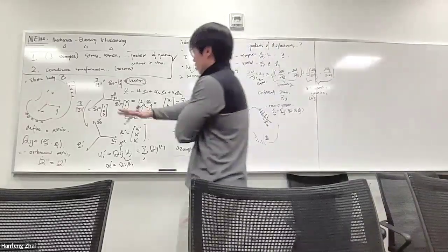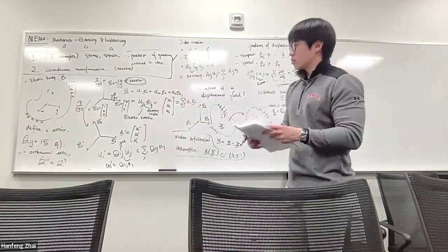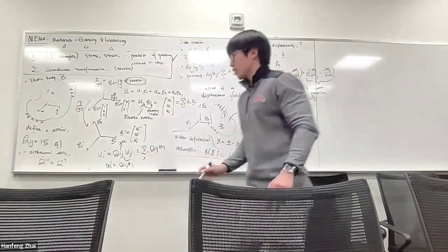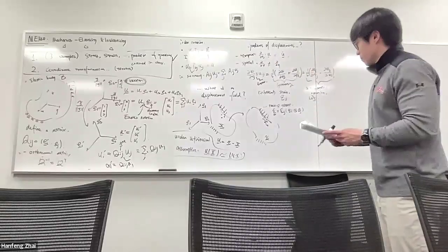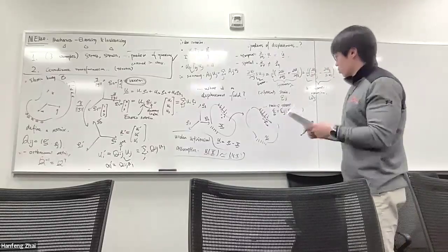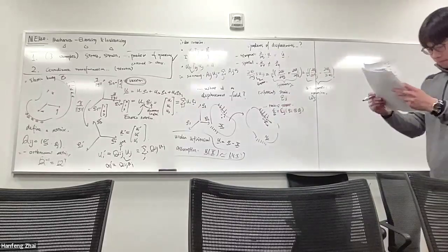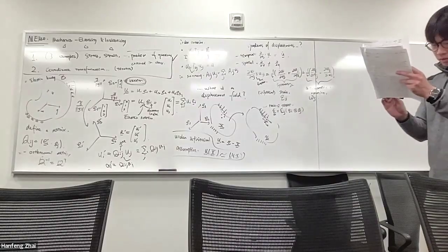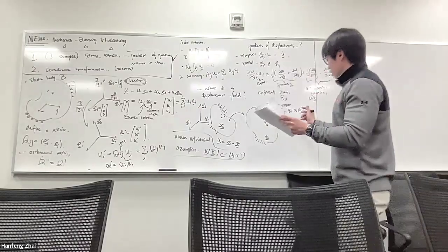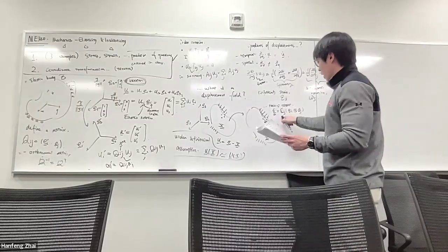As we already introduced here, when you want to transform the coordinate system to represent the displacement vector, we have two coordinate systems. You need a rotation matrix Qij to represent the transformation process. Here, since epsilon is a second order tensor, it has two indices. So we want to transform the coordinate system. There are two indices. We need to multiply the rotation matrix twice to rotate i and j.